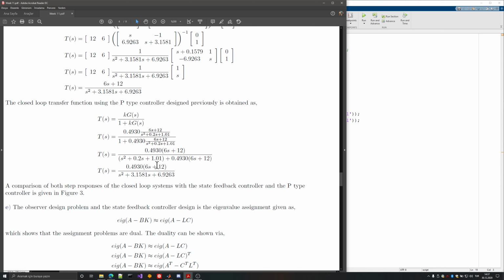You just need to have a controllable system, and that's all. If it's controllable, you can assign every pole family, every point on the complex domain to the system, and preferably the left-hand side. So you can assign also unstable ones. You can just grid the whole area in the complex region and you can assign them.